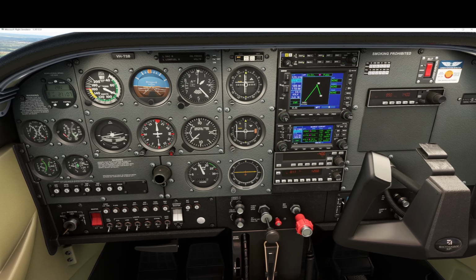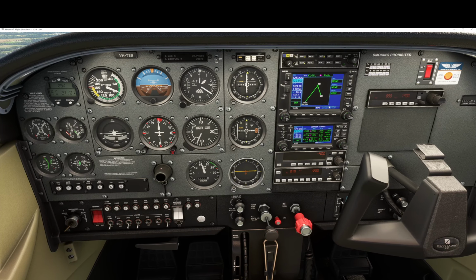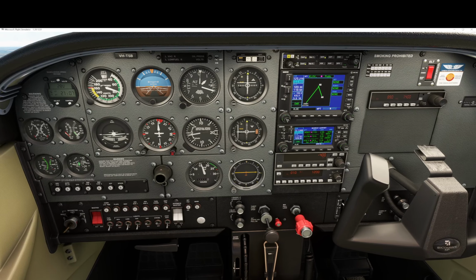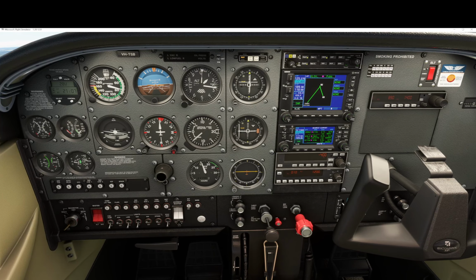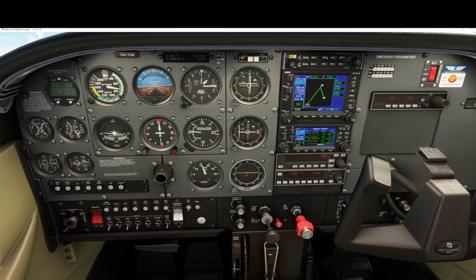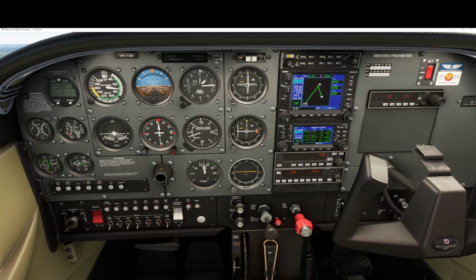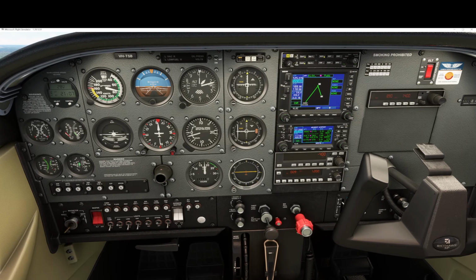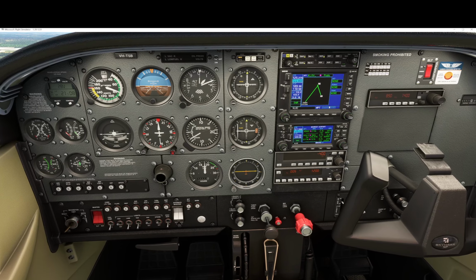I'm still below the glide slope. Still below the glide slope. I'm going to trim it now to hold this a little bit level until I can pick the glide slope up again. Get it back on the lateral course. That course is a little bit over to my right. And we're back on the glide slope again. Just about got it lined up.